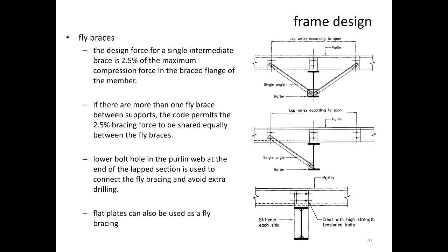As I say, that has got a cleat plate, which comes up and picks up the purlin. It will also have a cleat, a gusset, that comes at that corner and then picks up the purlin as well.